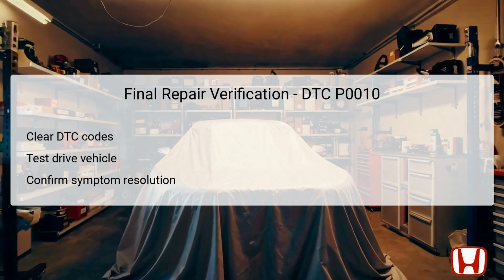Upon completing repairs associated with DTC P0010, it's crucial to conduct a final verification of the work performed. Begin by clearing any stored Diagnostic Trouble Codes, DTCs, in the PCM, as this will reset the monitoring system. Following this, a test drive should be undertaken to ascertain if the symptoms have been effectively resolved.